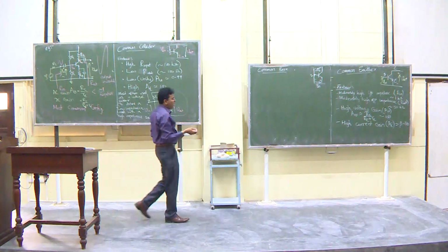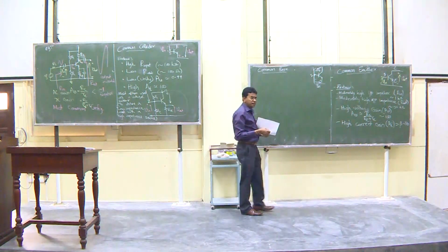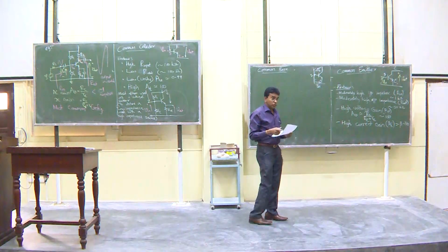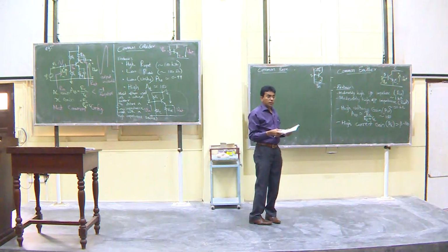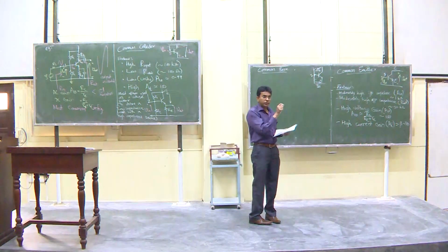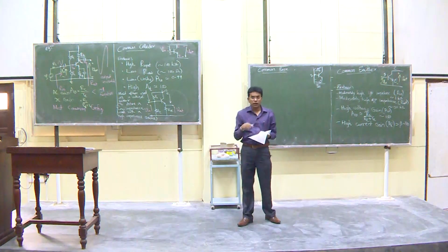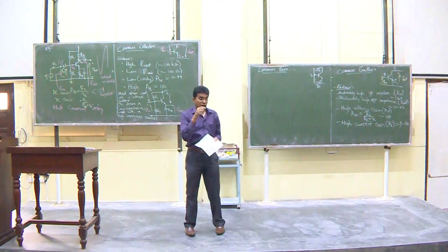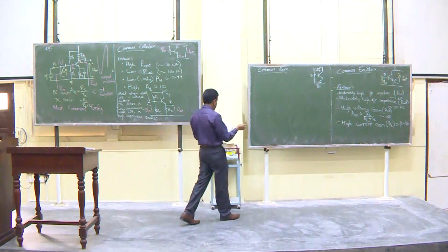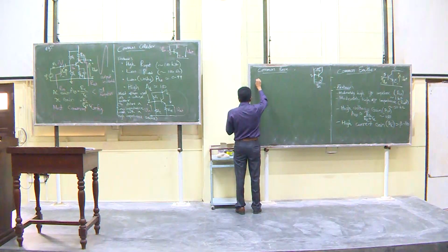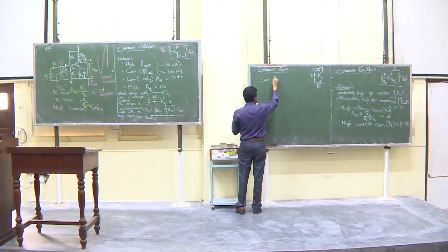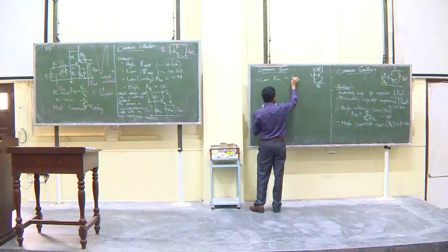You might think IE is slightly bigger than IC, so why not use that? You will see that the voltage is much bigger in the collector than the very small millivolt range voltage in AC conditions for the emitter. So therefore, this is basically what you have. The features are: low input impedance, in the range of 20 ohms.